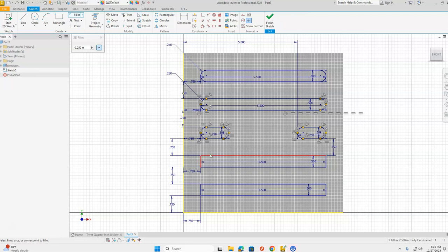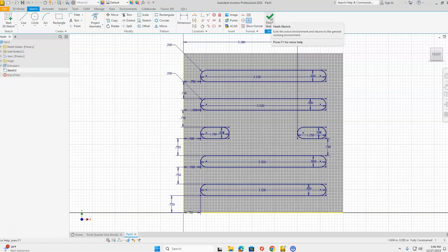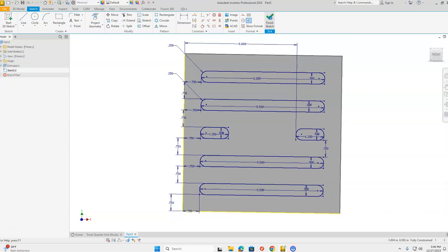And we got 2 more rectangles down here at the bottom in order to do as well. Make sure you take a look and don't forget any of the corners. Excellent. Once we have those all done, press Escape. Do a double check to make sure you have all the corners rounded over with those fillets. Once you double check that you have, click green check mark Finish Sketch at the top in the ribbon bar.